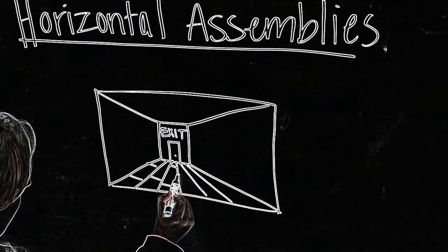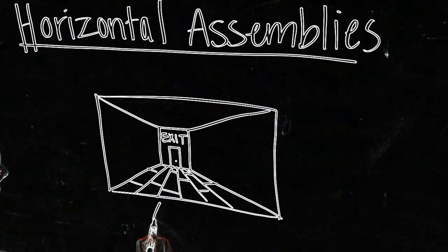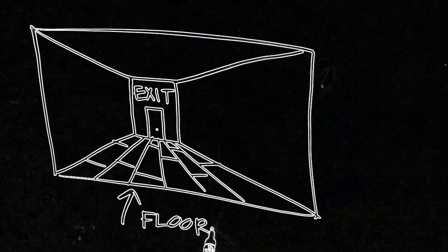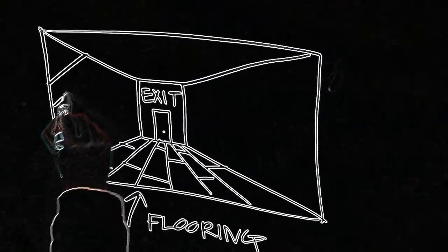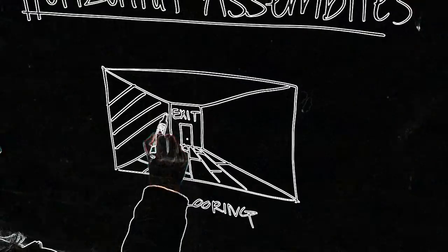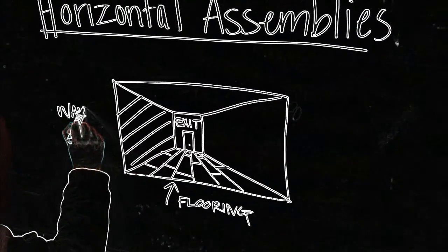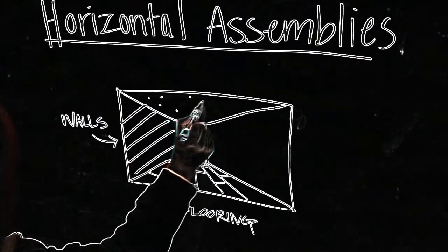Where fire barriers and horizontal assemblies meet, the joints must be sealed. Openings and penetrations are limited and must be protected as well. When the walls, floors, and ceiling assemblies surrounding an area have the same fire resistance rating, it creates a complete compartment or enclosure, both vertically and horizontally, like a four-sided box with a top and bottom.